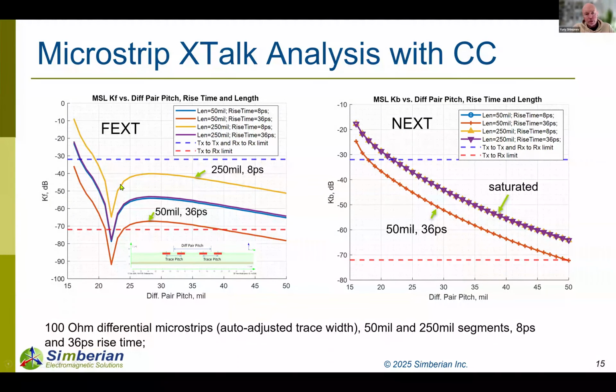So, but you can see that the smallest crosstalk happens at shorter lines and at longer rise time. So this formula basically relates length, rise time, and so on. You can experiment with this and see how it behaves. Rather than remembering what it is, you can directly do it in the computer. So with near crosstalk, if we have too short a segment or longer rise time, we can see that it's smaller, but then it saturates.